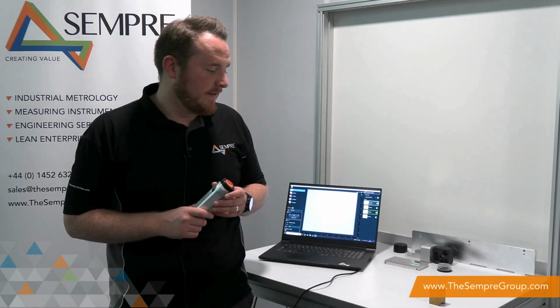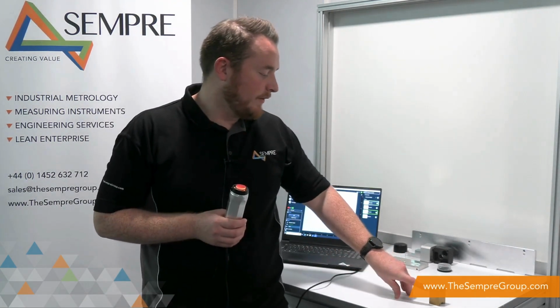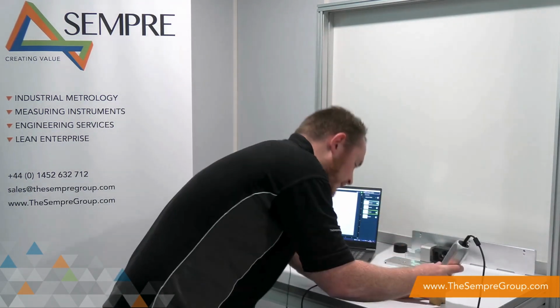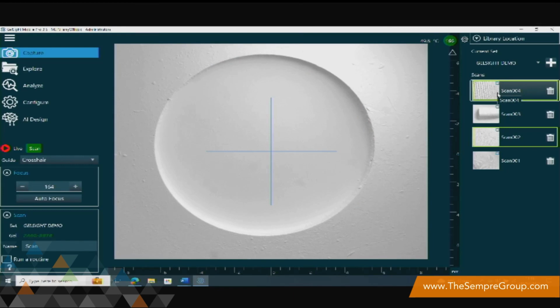We can use the GelSight system for dimensional checks. On the example I'm going to run through here, we've got a hole diameter as well as the angle and the length of a chamfer. So I'm going to bring the GelSight system to the hole diameter to start with. I'm going to place it over, and I'm going to take a capture.